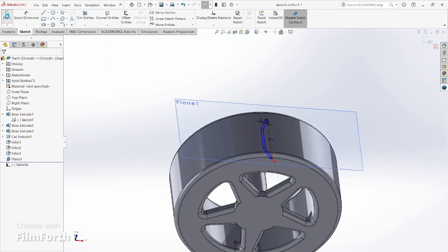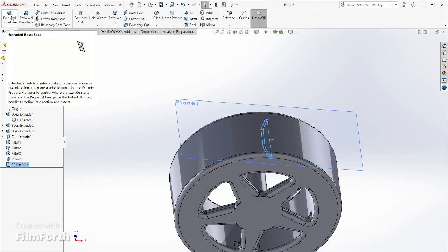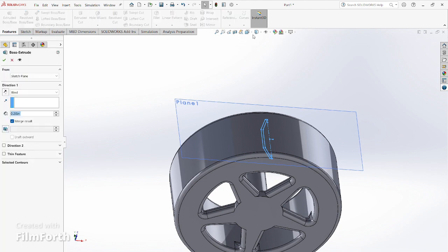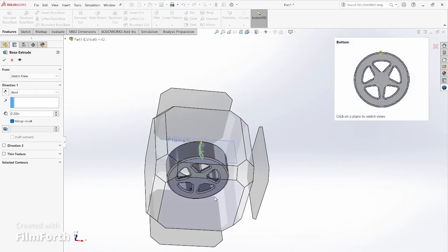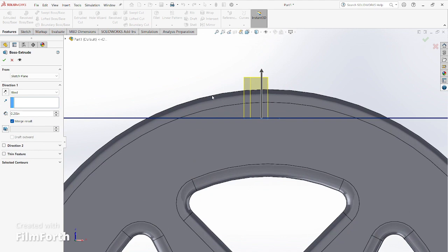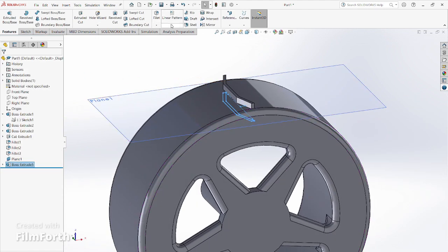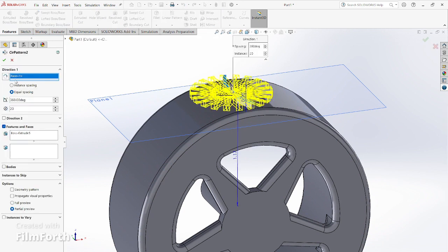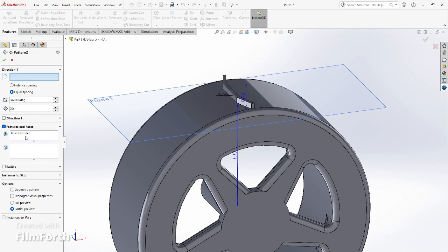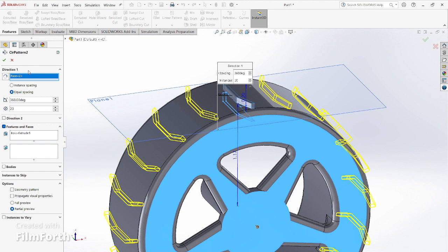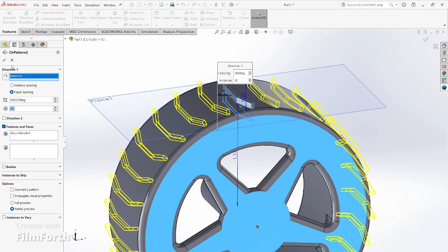And what I'm going to do is exit, features, and we're going to extrude this upward. I'm going to bring this guy to a different side view. There we go. So this is perfect. Check it. Then we're going to do the same thing, circular pattern, the part that you want to try out. Whoops, not the base, delete that. Let's extrude it, good. And the face of it right here. There we go. And then either if you want to do 20, let's try 30. There you go.